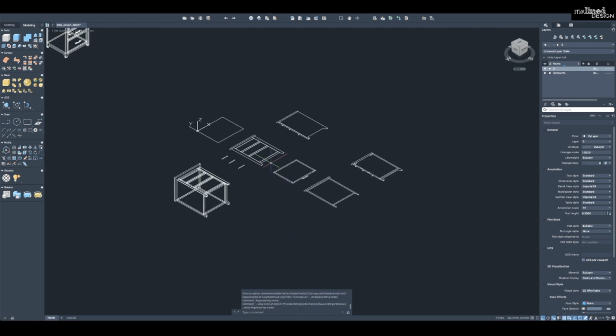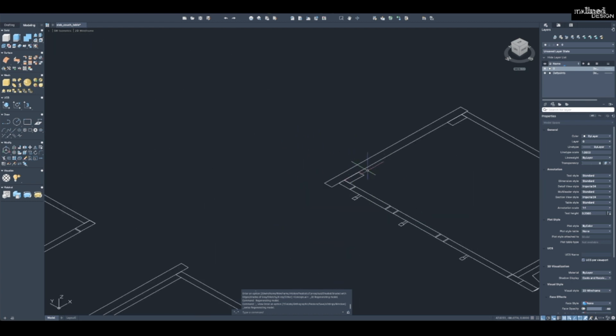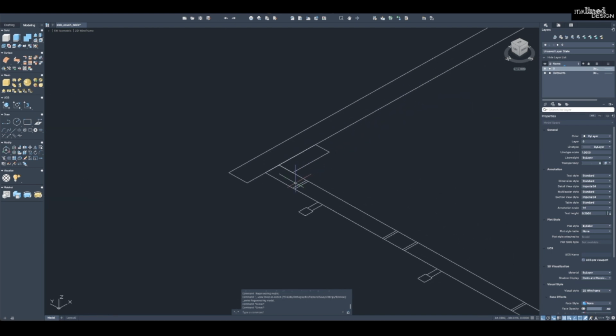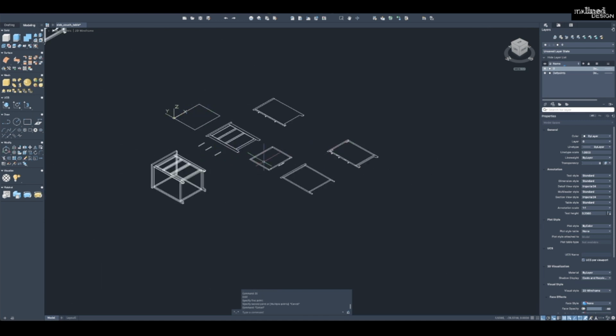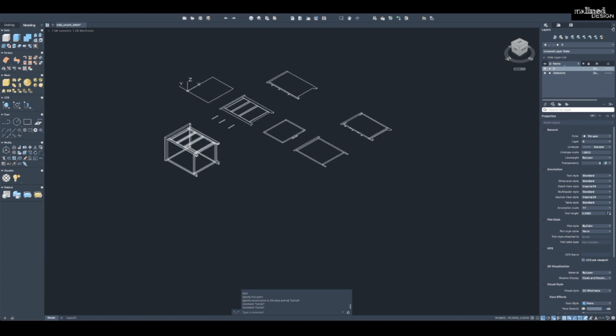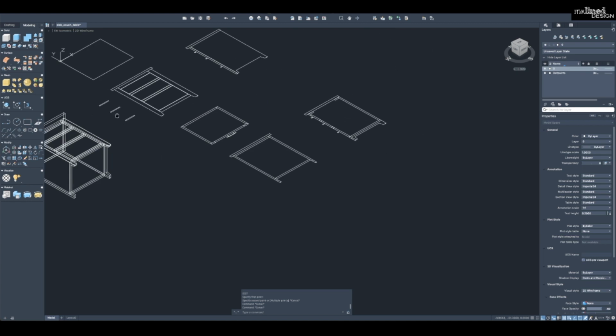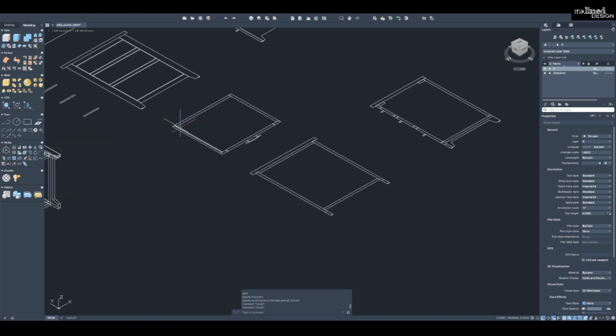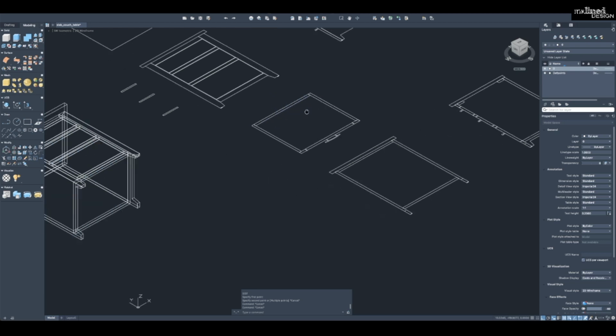Southwest isometric again. Okay, so now, really, the top has a couple, I think they're 2-inch stretchers for attaching the top across there. You could make a hole like 2 inches in front, 2 inches in back, and on the sides to attach. And you also want to, because we will work on this top a bit, as the top will expand and contract. So you can do your center ones without slotted holes, but towards the outside, you definitely want to use a slotted hole pan head with a washer to allow the top to expand and contract.